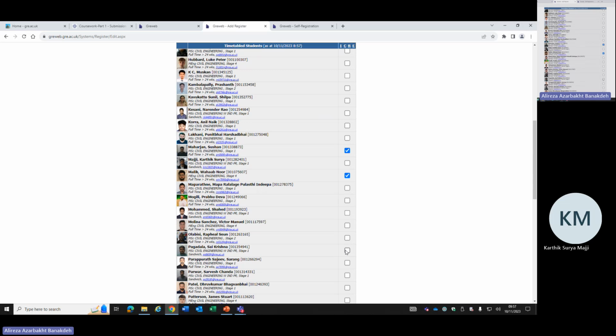Fixed. Why? Because this is X, this is Z, this is Y. We will control this. Y is free. But X means this one, this is closed, this is closed, but this is free. Right? Y should be free, those two should be fixed. And with this one, the same, but this one, translation in Z is also free. The rotation about Y is free.